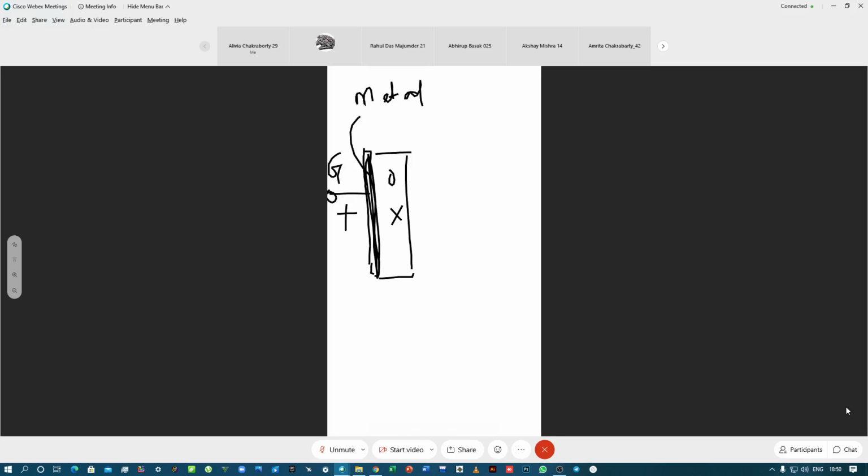So what would the energy band diagram be like? First we start with the same notation. Since there is no current flowing, we assume that the extrinsic Fermi level maintains a constant level throughout the entire P region. So that is EF, the extrinsic Fermi energy level. Okay, and now what happens? There is accumulation of negative charges. This is a p-type substrate, no doubt.